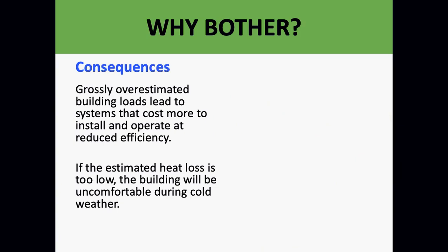Oversized air conditioning does not properly dehumidify. I call it the cold clammy effect. You'll walk into the house and it will feel moist, almost like a walk-in refrigerator. Feels moist, feels cold and clammy. It just is not a comfortable environment.